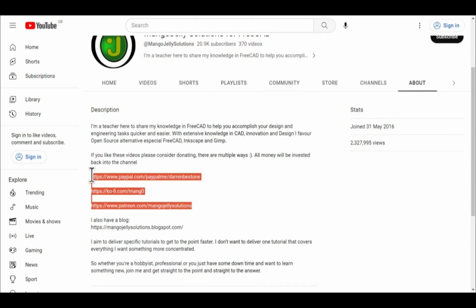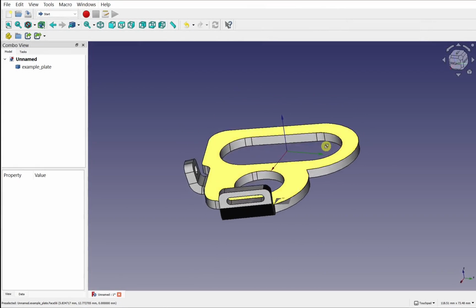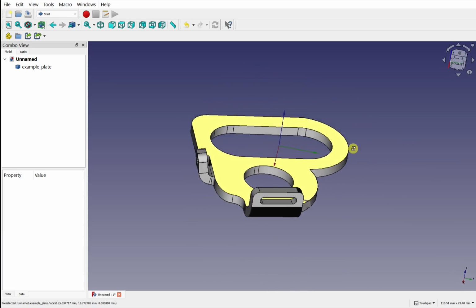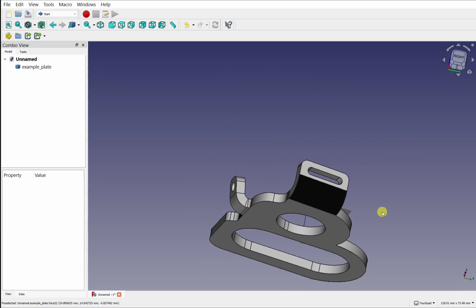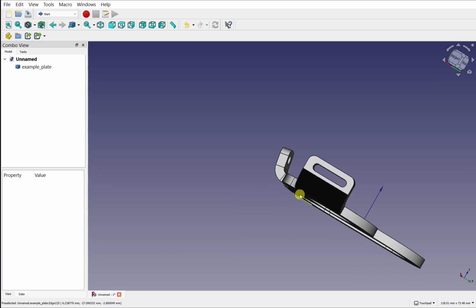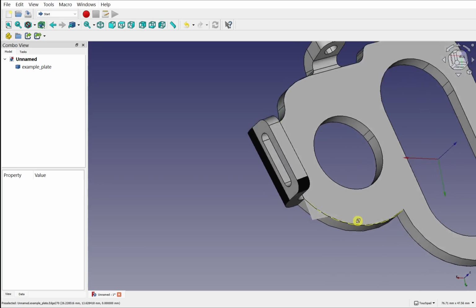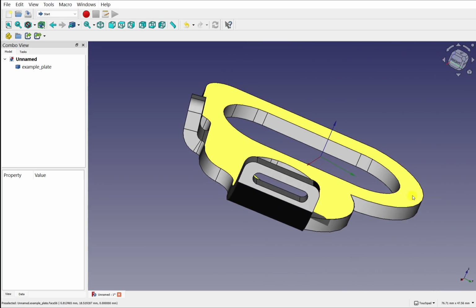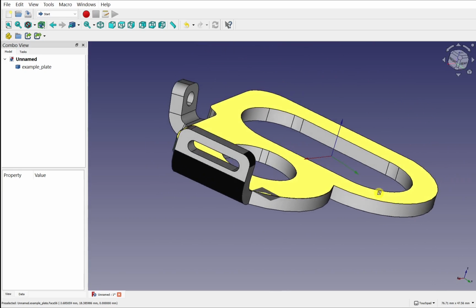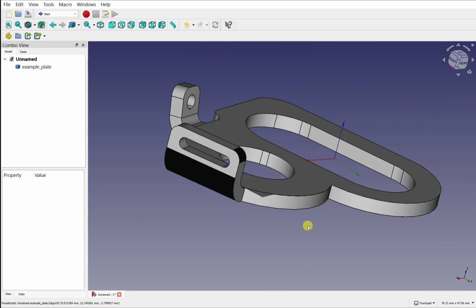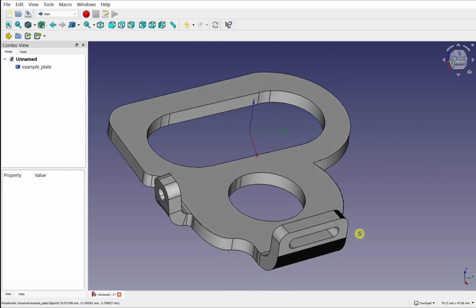So this is the object I'm going to unfold in FreeCAD. If we look at the object, you'll notice that there are a few errors in here. These black faces that are coming up show that FreeCAD can't calculate this face, and we've got an anomaly here as well. I've introduced these anomalies into this model, so I've got a model that's far from perfect to work with. There are also a number of flipped normals, intersecting faces, etc. So I've made it hard on myself to actually unfold this. And I'm going to show you a way to easily unfold a model like this that has these errors.